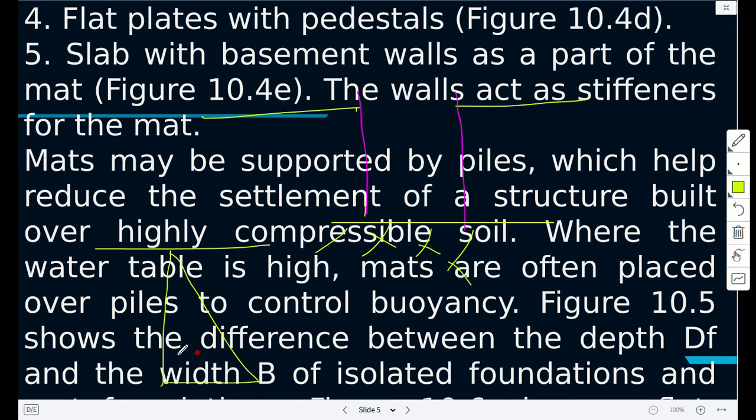So the pressure, the lateral force applied to the wall increases as you go down. So because of this, if you don't support this with a retaining wall, let's just call it a wall, in weak soil, the soil will collapse.